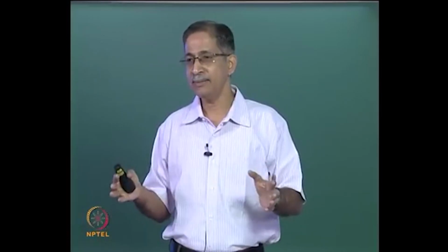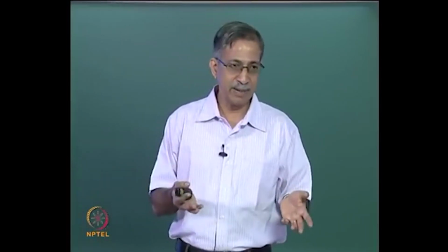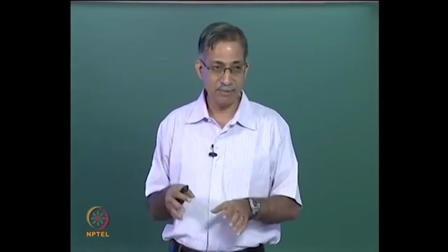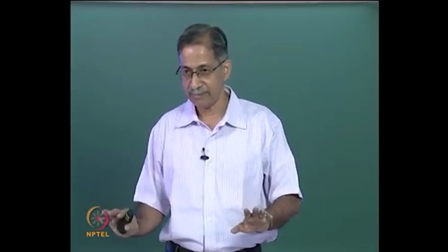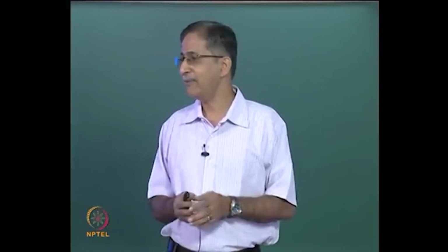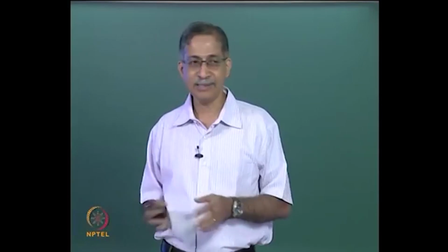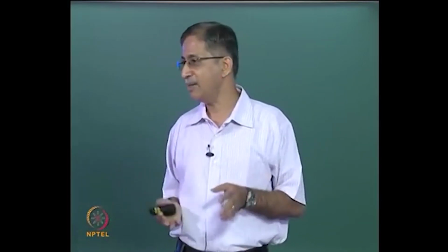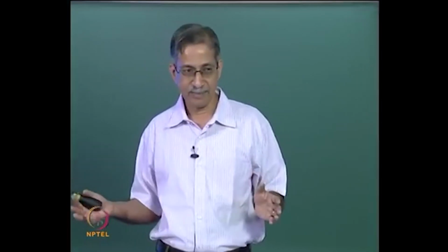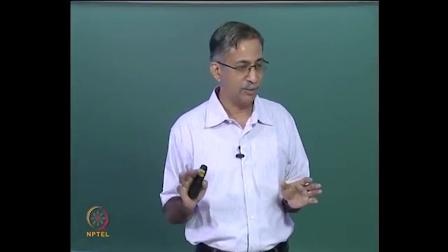The knowns are the loads that are applied, the unknowns are the reactions and the internal forces. That is a force field. As far as the displacement field is concerned, usually everything is unknown. The displacements are not known and the bar elongations are not known. If we wish to, we should be able to calculate everything, and that is the whole idea of doing structural analysis.